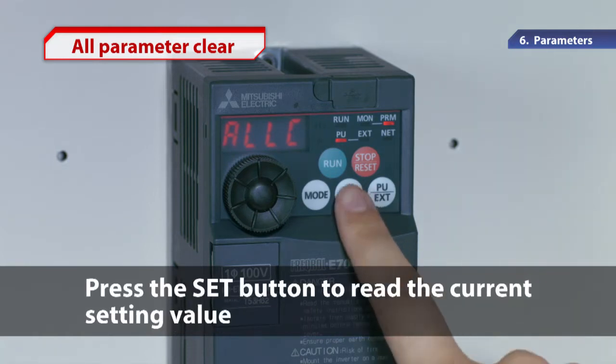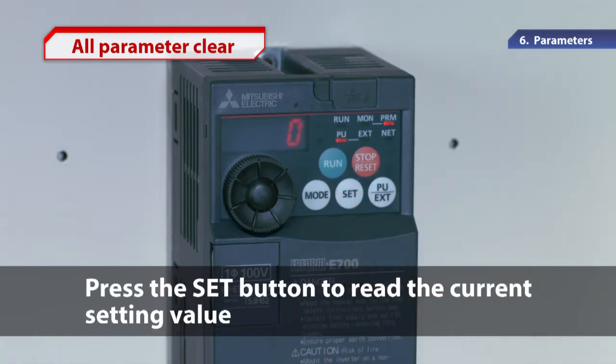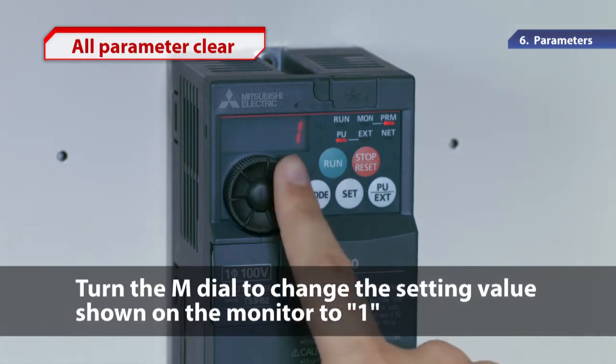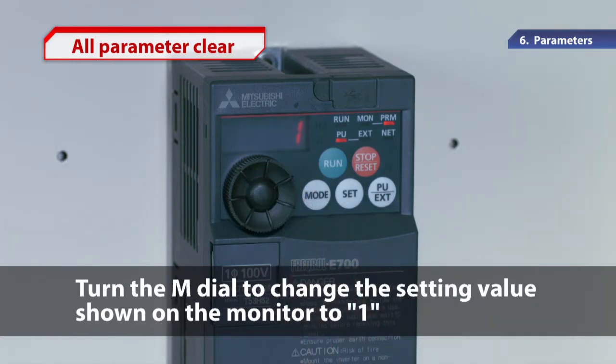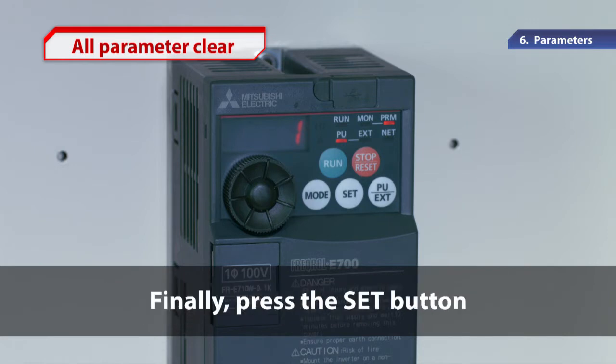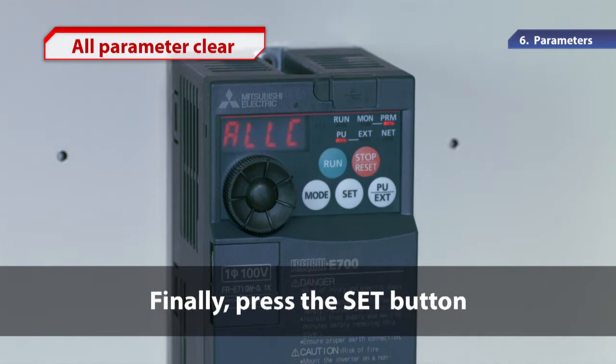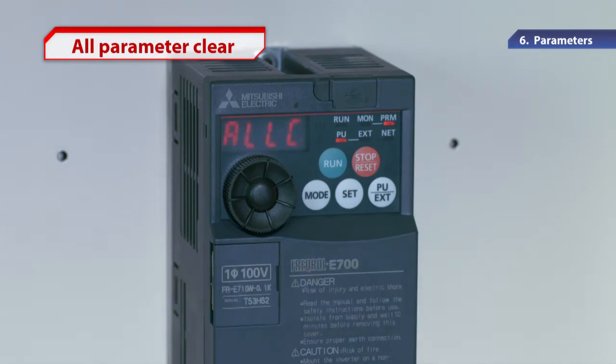Press the Set button to read the current setting value. Turn the M dial to change the setting value shown on the monitor to 1. Finally, press the Set button. After that, the 1 and the ALLC lights will flicker alternately. Now the parameter settings have been initialized. It might be better if you keep this useful function in mind.